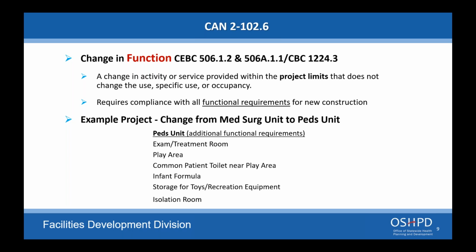If you're going to do a zero construction project, a lot of people aren't used to that, including our teams. We don't see a lot of them, but they have come through. So I would definitely recommend scheduling a meeting and talk through the process to make sure you're thinking this is going to be a zero cost, but yet all of a sudden you do have these actual triggers that do require some upgrades, something you might not have thought of before, such as converting patient rooms to offices. Now you have to do things with the doors or the egress or the corridors. So you have to be really careful about that, and I would definitely meet with us prior to doing that.